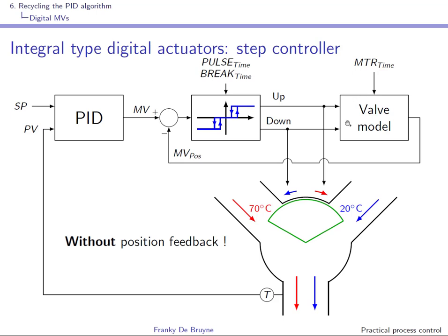Of course, the output of the model is not going to be 100% precise, and with time it could be that the output will be off with respect to the actual valve position. But what you can do is use these binary signals that signal when the valve is entirely closed or entirely open.